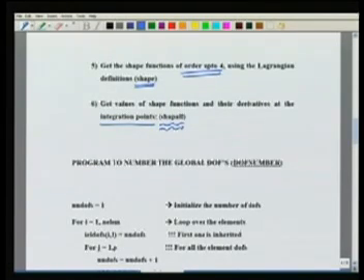Why was this needed? This was needed for our element calculation, because as we are looping over the elements, trying to compute the element stiffness matrix and the load vectors, we do not want to call the shape function program at every integration point, get the output of the shape function, use it, and then go to the next one. This causes repetitive work, and that costs in terms of time. So what we said, over the integration points, since they are the same for each element, we will call the shape functions, store them away, and in the elements, as we go and do the element calculations, we are simply going to read out those values from this stored set.